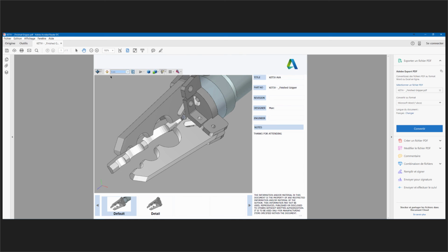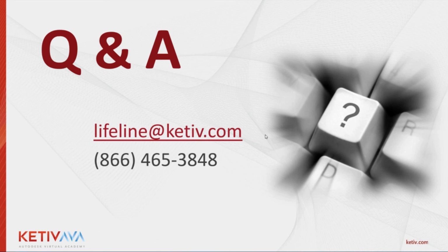Absolutely. And then the last short thing here from Daniel. How do you translate a mesh file to an Inventor 3D model? That's a little different. Great question. We have something that used to be called Autodesk Memento that is now called Autodesk Remake, that allows you to turn a mesh into an OBJ file, and then from OBJ you can actually turn that into a solid. It's not a straightforward workflow, but it's working. There's some YouTube clip about it on our channel, and I think you guys did one as well. So yeah, I can get back to you for that one.